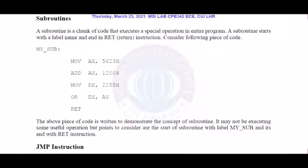What is the difference between a label and a subroutine? How does a compiler differentiate between a label and a subroutine? Basically the difference is the RET instruction. That instruction stands for return. For making a subroutine you need to define a label, then you need to write the portion that you want to be part of that subroutine, and at the end you need to write RET, which makes that specific portion a subroutine.